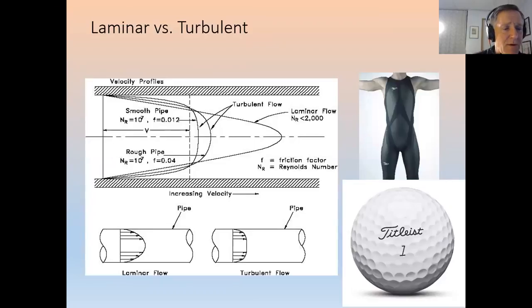But this is expanding on what we talked about before with what was called the fully developed flow, where I showed you an image of the fan and how air blew through it. And this is showing you cross sections of piping, the velocity profiles of piping of different types. And you'll see numbers like Reynolds number, which is basically the ratio of inertial to viscous forces. We'll look at that later. So you have different types of behavior when you have high flow versus low flow speeds. High flow speeds will generally become turbulent, and low flow speeds are laminar.